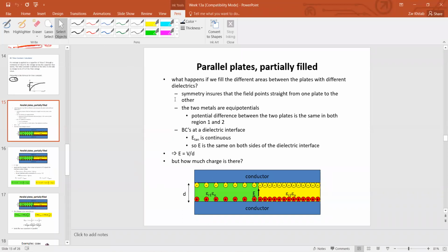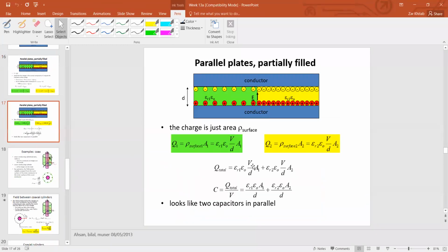Okay. Last time we also saw this kind of arrangement for the capacitor. What if we have capacitors lying in this way? And we concluded that we end up again with two capacitances, but this time the two capacitors look like they're in parallel. Why? Because this yellow capacitor is between VA and VB. This green capacitor is between VA and VB, the same voltage. So the green and the yellow capacitor are both between the same points.